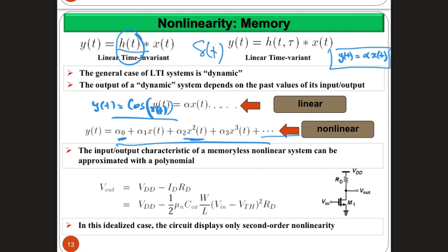All of that is dependent on Vgs, but when you move between linear and saturation, you also consider what the drain voltage is in comparison to the other quantities. Anyways, most of the time when we use this for amplification, we want to be in the saturation region. Amplification is better done when you are in the saturation region of the MOSFET transistor. In that region, there is a particular relation that allows you to calculate the current going into the drain. Why do I need to be able to calculate the current going into the drain in this circuit? Because the general relation between the input and the output in this circuit is what?